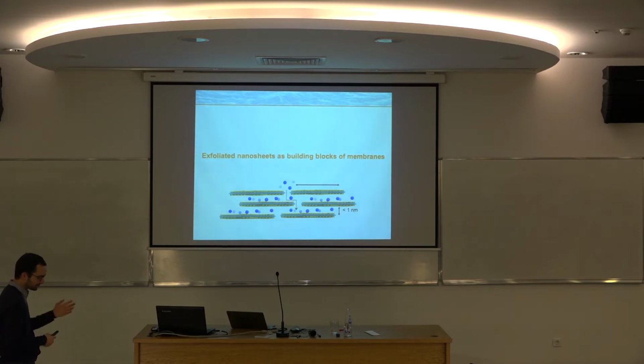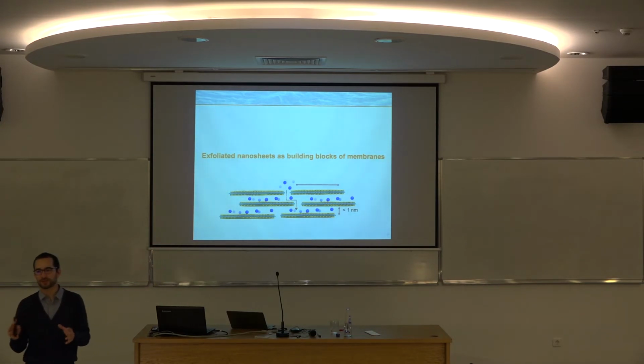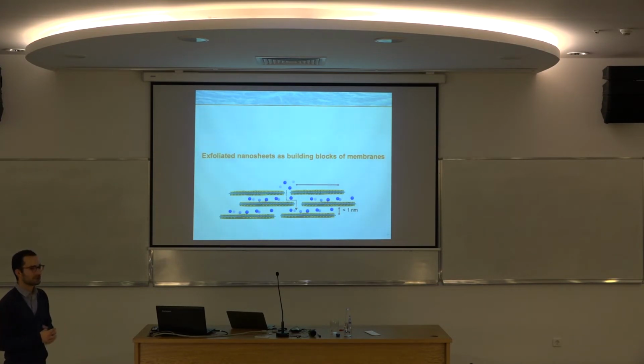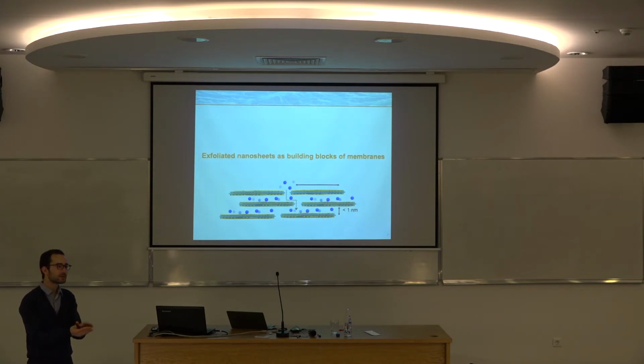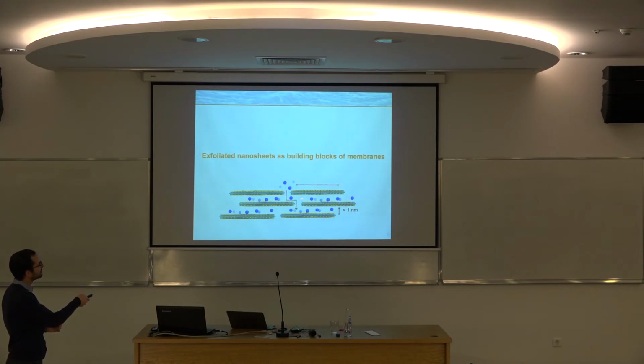Since I moved to this membrane institute, one of the things I wrote in my application was to use these TMDs, or these 2D materials, to make membranes. One way to use two-dimensional materials is to restack them to make nanocapillaries, where you can, in principle, control the spacing between the nanosheets, and this interior spacing can sieve molecules depending on their size. The idea we had was: we can functionalize, so why not functionalize these TMDs, stack them, and have nanocapillaries with different surface chemistry.